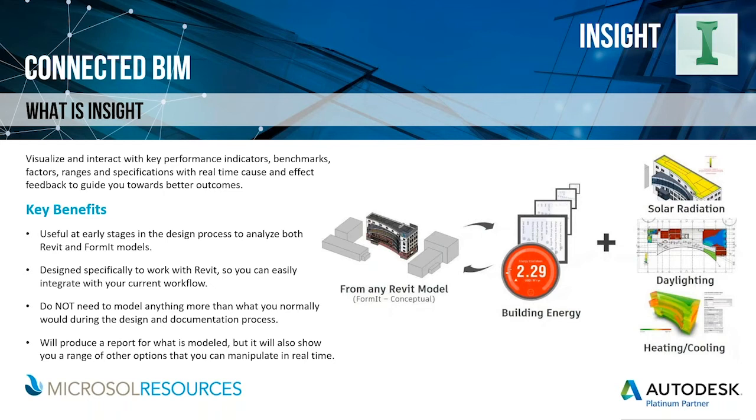The energy model created by FormIt or Revit will provide an accurate representation of your model with minimal effort from the engines. This allows you to integrate energy modeling with your current workflow, which is ultimately what we're trying to supplement here. So you can certainly go as far as specifying thermal properties, space occupancy, lighting, equipment, schedules, all that type of stuff within the element properties to inform the Insight analysis, but it is certainly by no means necessary.